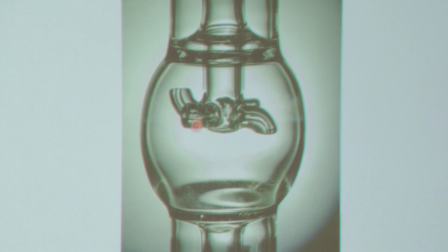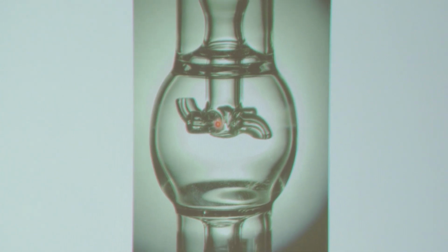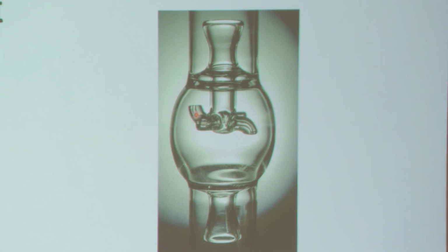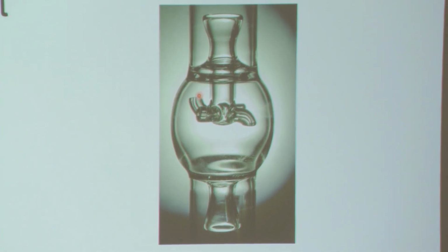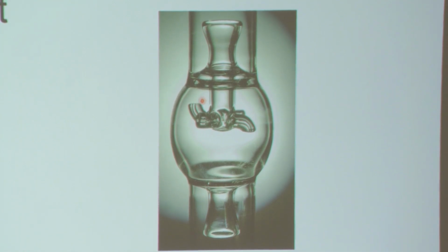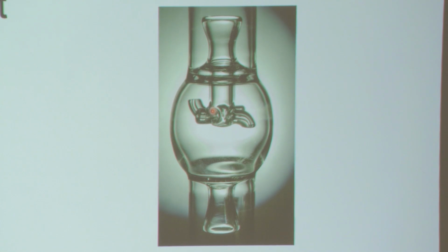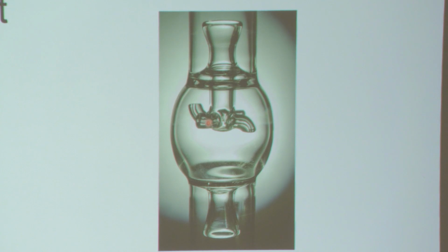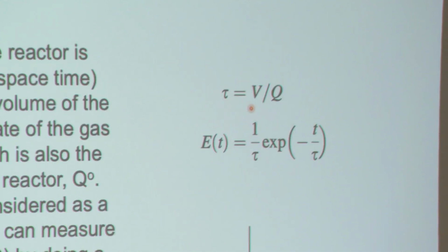The inner diameter of these is about 1.5 to 2 millimeters. So you got to make sure that the gas flow rate is not too large. If it's too large, you get a choked flow through these very tiny nozzles. That's not good. Also, if it's too large, you might get a shock wave because the gas velocity coming out of these very small nozzles is too large, entering into the larger volume. So you create some micro shocks which cause disturbances in the flow field. So you got to optimize your flow rate so it's not too large, and at the same time it's not too low, so you don't lose the well-mixed regime.